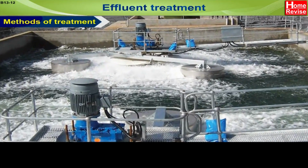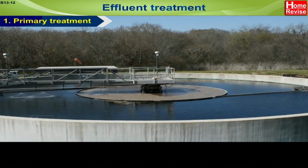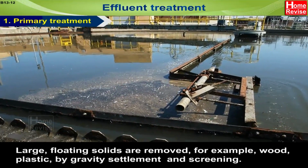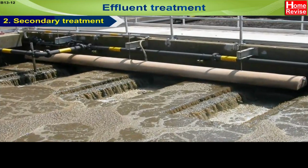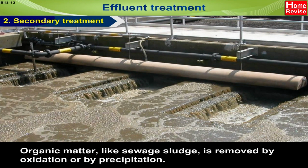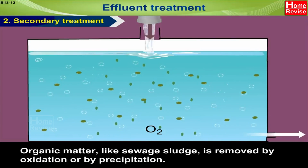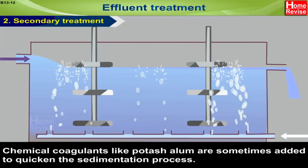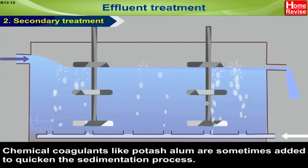Methods of treatment. Number 1. Primary treatment. Large floating solids are removed, for example wood, plastic, by gravity settlement and screening. Number 2. Secondary treatment. Organic matter like sewage sludge is removed by oxidation or by precipitation. Chemical coagulants like potash alum are sometimes added to quicken the sedimentation process.